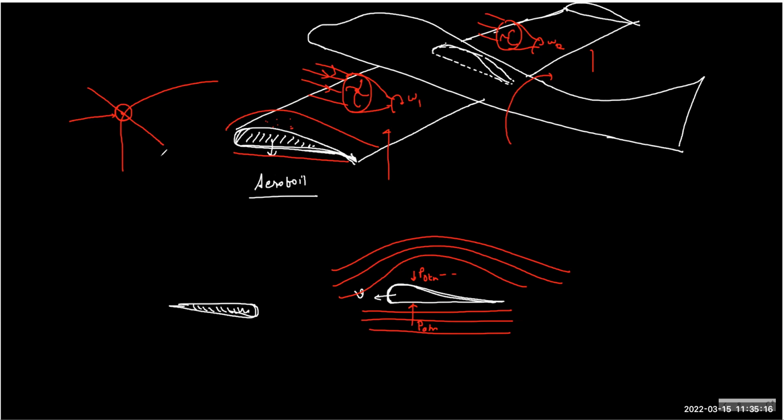So you can see that the basic concept of lift and the omega 1, omega 2, the rotational velocity variation will create a different amount of lift, and you can think of this as a torque, you know? So by changing the force value, I can create a torque. If omega 1 is equal to omega 2, then what will happen? It will remain horizontal, isn't it? So by varying the omega, we can keep on changing the torque value, and once torque will change, it will rotate.